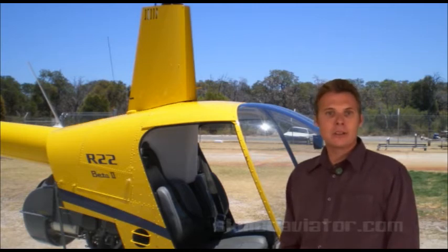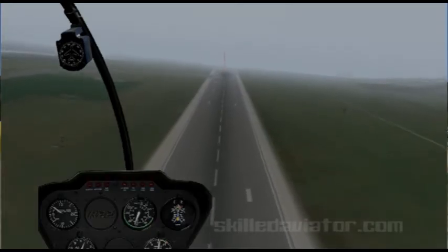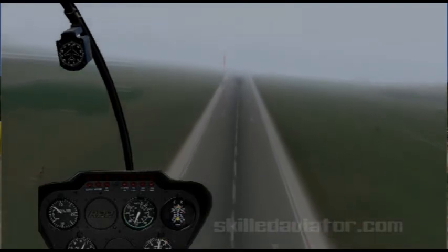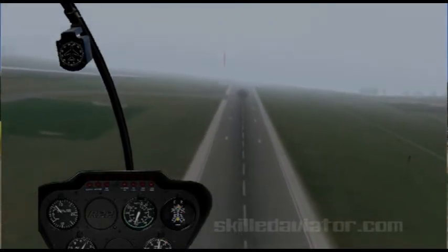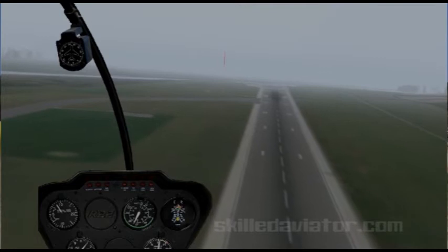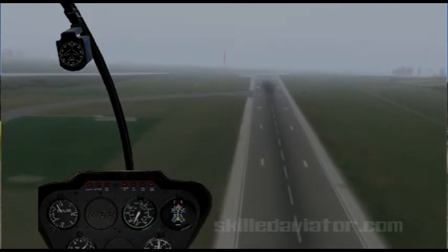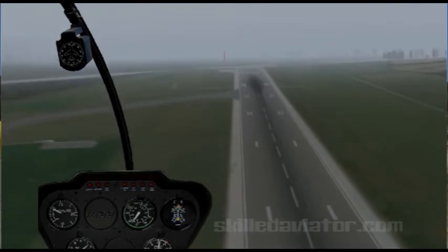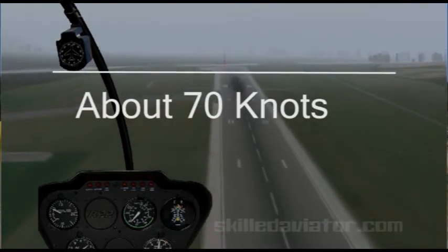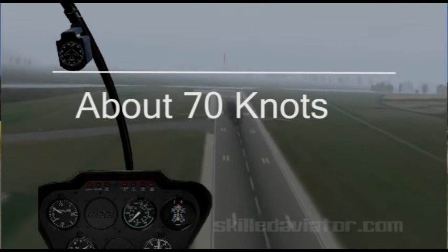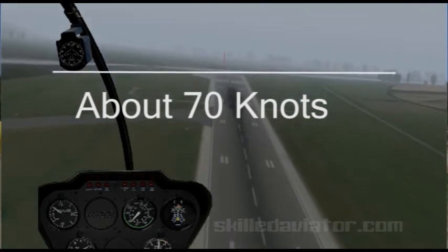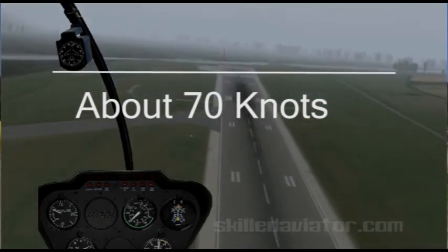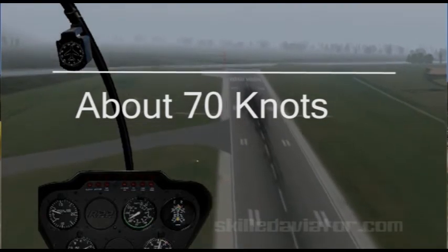When you are flying and your instructor gives you an altitude to maintain, try to keep the aircraft straight and level. Look at the horizon and try to keep it horizontal with the aircraft. Keep the helicopter in balance. Also try to gauge how fast the aircraft is going by looking at the attitude of the aircraft. If the aircraft is flying at 70 knots, look at the horizon and match that point with something on the windscreen, even a dead bug.